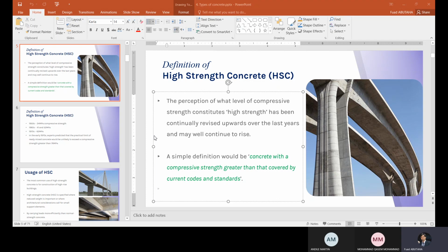Okay, in other words, will a high water content or a high water cement ratio increase or decrease the strength of concrete? I think decrease. You mean that the more water content, the lower the strength? Yes, sir, because it will cause segregation. Okay, this is correct that it will decrease the strength, but